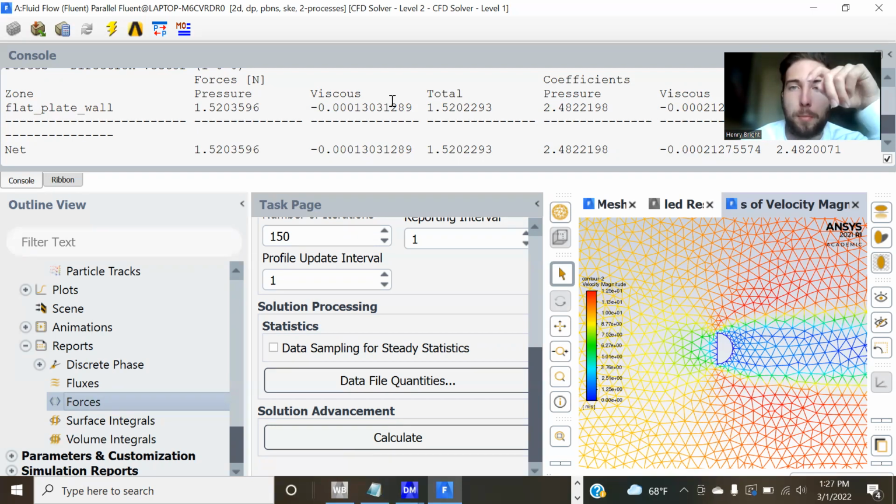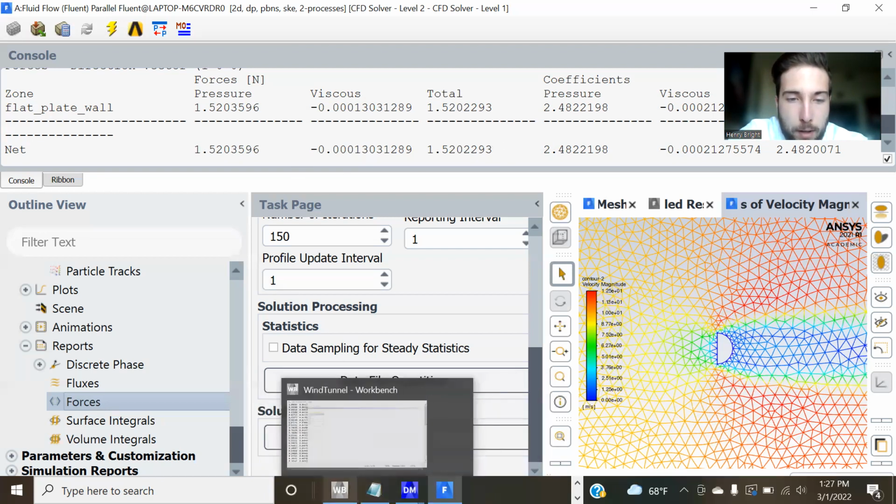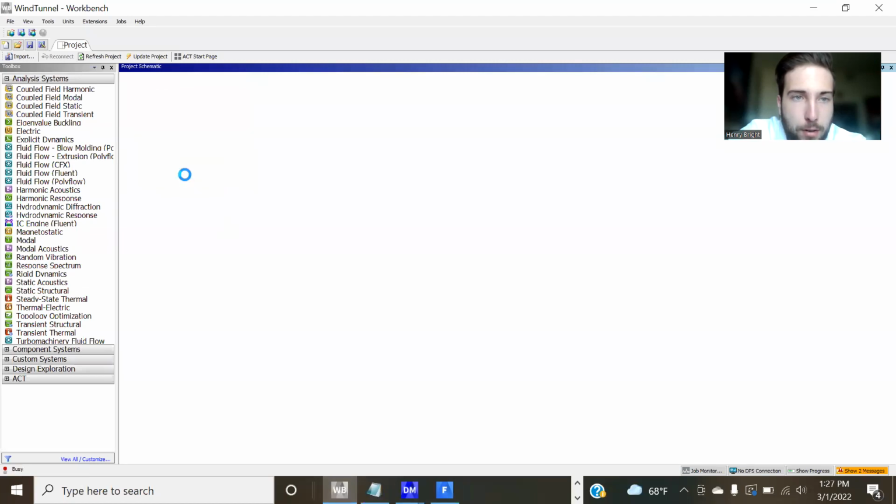And then that will be multiplied by the diameter of the cylinder. That's like the critical length. So basically it's going to be a drag coefficient per unit span, since we're just in 2 dimensions. But that's how we're going to do it. We're going to actually do it by hand, but you'll want these drag force numbers that you calculate, mainly the total drag force.